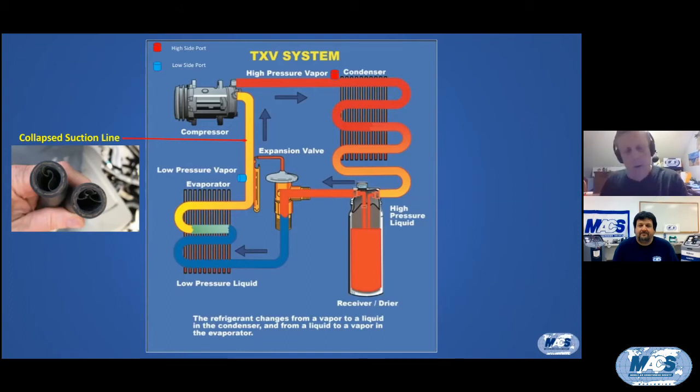The same thing wrong with all of them? I said, it's pretty unlikely. He said, but this compressor, he slammed his fist on the desk. He said, this compressor won't pump over 135 or 140 pounds. I said, well, you could have a restriction in the system. He said, no, I don't have a restriction. He said, if I have a restriction, I would have extremely high side pressure. I said, well, maybe depending upon where the restriction is, but a restriction can actually cause your high side pressure to be lower than it might be.